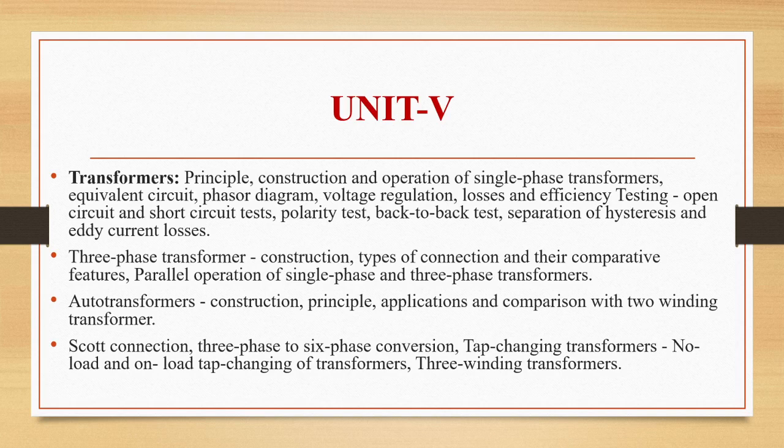And limitations also we have seen for auto transformers. So the use of auto transformer is very limited, okay? And construction wise, if we see auto transformers, it is also of step up and step down type. It will also have N1 N2 number of turns on primary and secondary windings, okay? But a part of the winding will act as a primary winding and a part of it will be acting as a secondary winding.